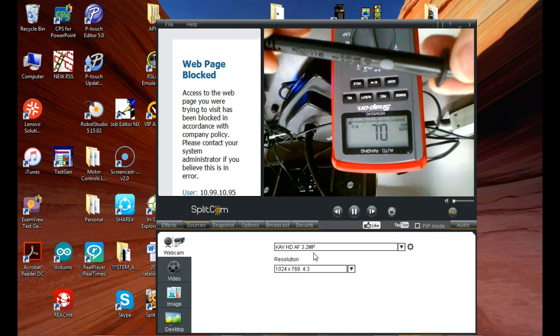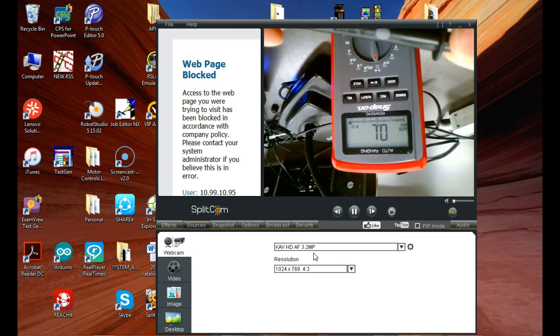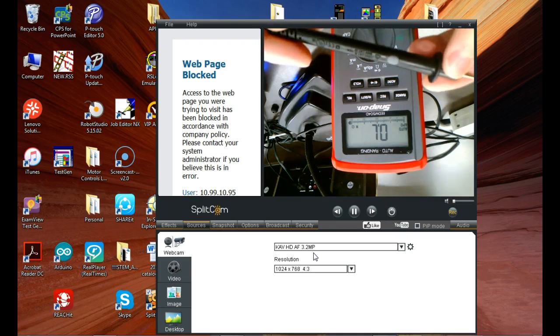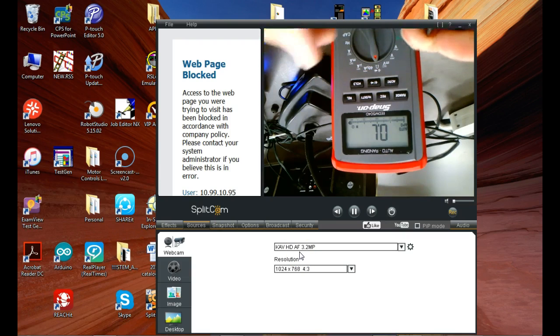these meter leads, we're actually getting to where they're putting a category on the meter lead. So this says this is 1,000 volt Cat 3, 600 volt Cat 4. What type of voltage spike it can handle, we would have to go back into the chart. I'm sure after a while you would learn it. So the maximum range, if you want Cat 4 protection, that you should put your meter on with this lead right here would be 600 volts, right? But you'd have to have a Cat 4 meter. This is not a Cat 4 meter.